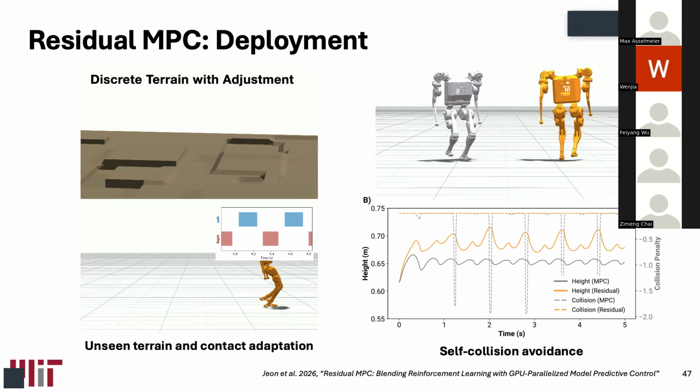The RL training from the beginning, is it going to be stable? You can't guarantee it's stable, but you can really help it by initializing all the weights of the residual policy to 0. It's a randomly sampled stochastic policy, so you have some torque noise, but if you initialize it to be small, like in the original residual policy paper from Leslie Kaelbling at MIT, they did the same architecture, initializing the weights of the residual policy to 0, and they had some pre-trained expert policy that they learned on top of.